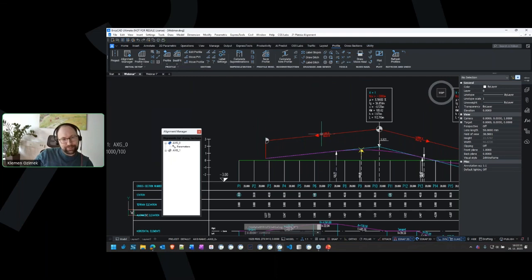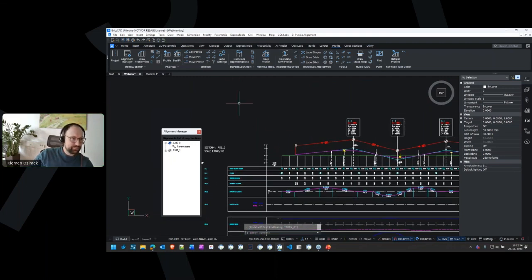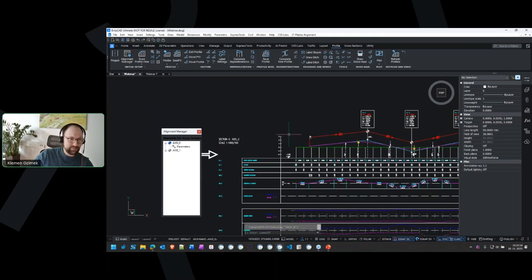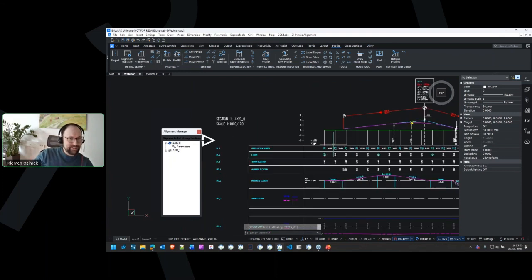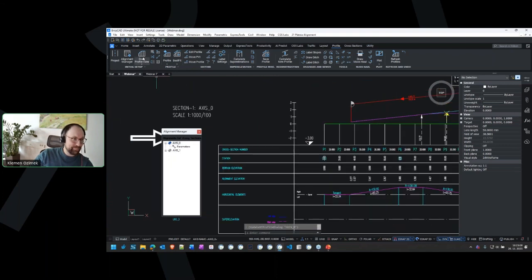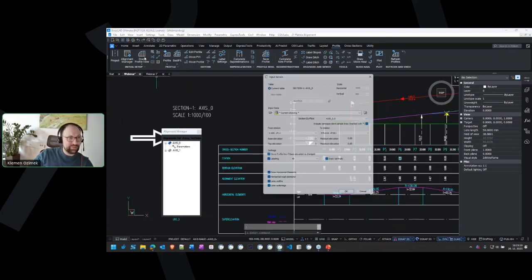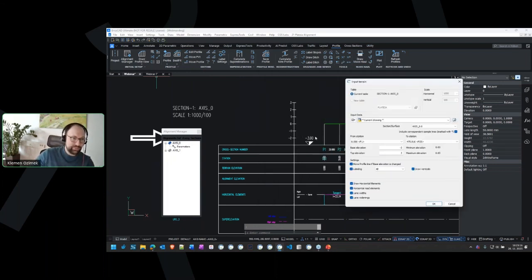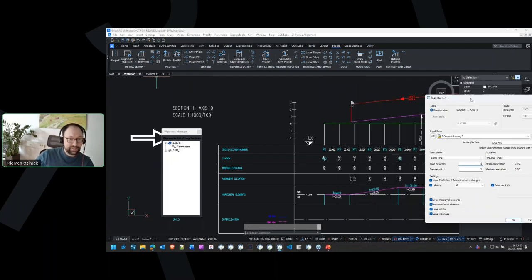Another use case is if you have terrain that is not flat like this, but has elevation that varies quite a lot. In some cases you want to change the reference height. For the profile view, if we go into this function here, we can change this base elevation, this reference height, to something lower, so that for plotting or similar you will use less space here.